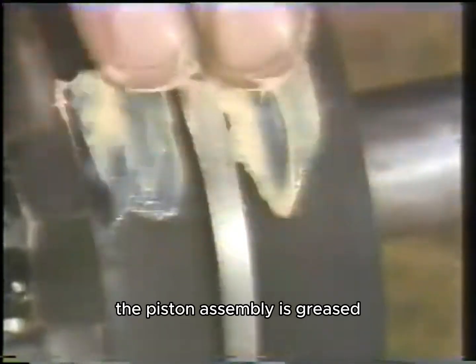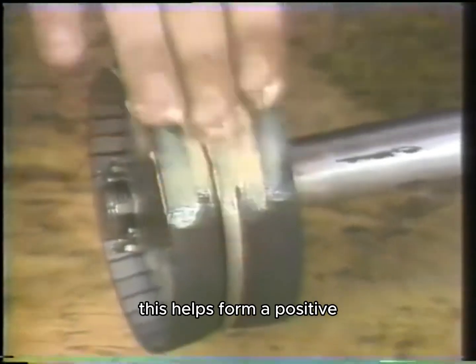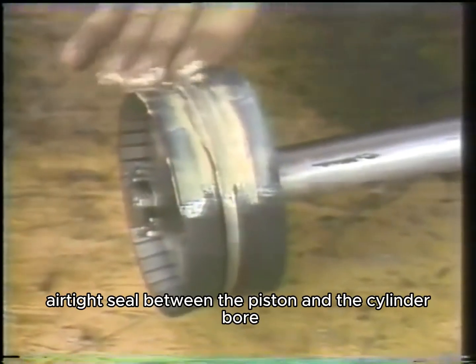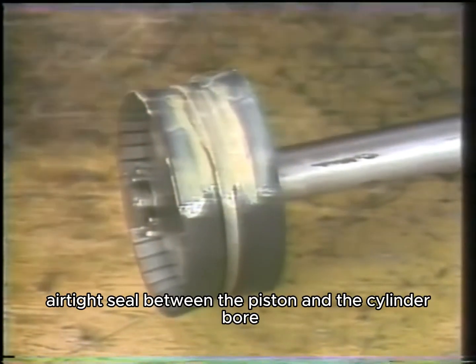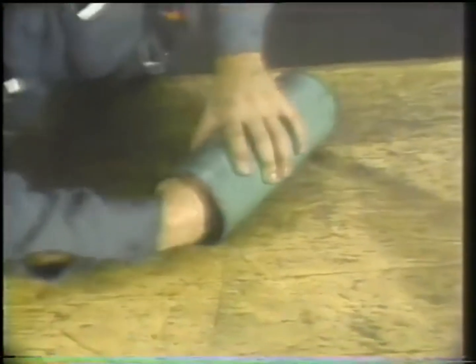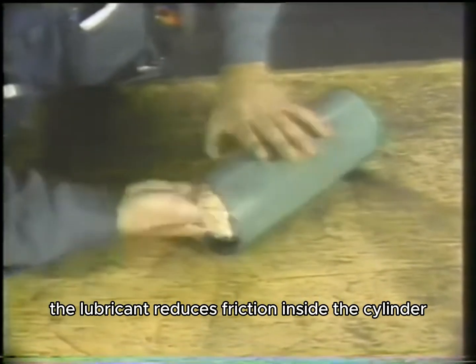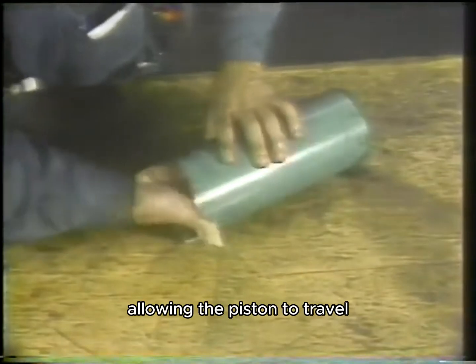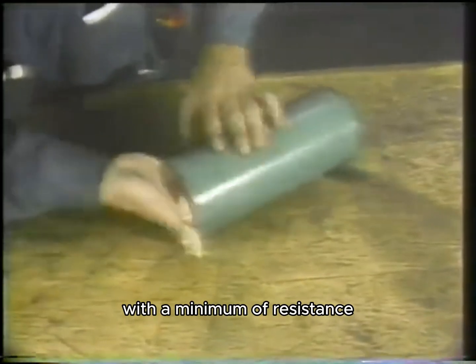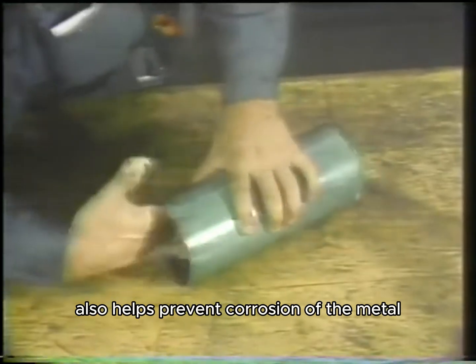The piston assembly is greased with the lubricant recommended by the manufacturer. This helps form a positive airtight seal between the piston and the cylinder bore. The inside of the cylinder also gets a coating of the same lubricant. In addition to its sealing properties, the lubricant reduces friction inside the cylinder, allowing the piston to travel with a minimum of resistance. An even coating over the entire bore also helps prevent corrosion of the metal.